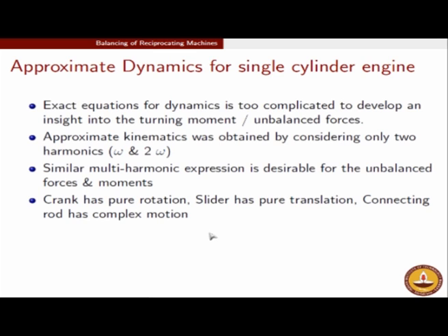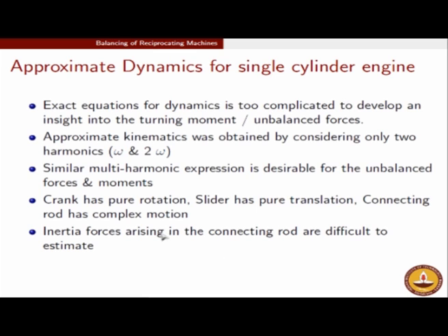So, what we try to do here is approximate the connecting rod in a nice fashion such that we are able to get around this difficulty. We will see how. Since the connecting rod has complex motion, it is very difficult to establish the inertia force associated with this complex motion, which is a superposition of translation and rotation. Through a computer it is possible to determine, but again, it is very difficult to get a formula out at this stage.